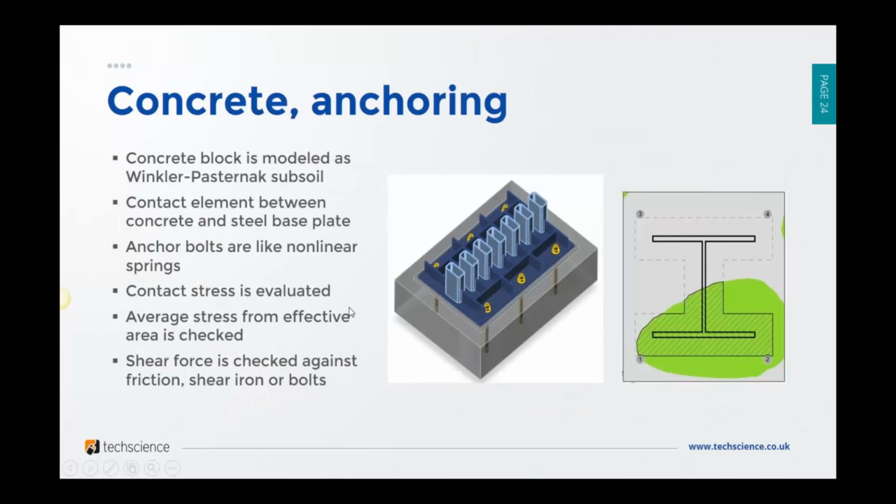The concrete is also modeled as Winkler-Pasternak subsoil, so it's not modeled by finite elements. But we use this model similarly to designing buildings. In each point of the mesh of the base plate, we have contact elements and springs, which represent the stiffness of the concrete block. We also take into account the mortar joint. Anchoring bolts are also modeled as non-linear springs, and of course all appropriate checks according to the codes are implemented.